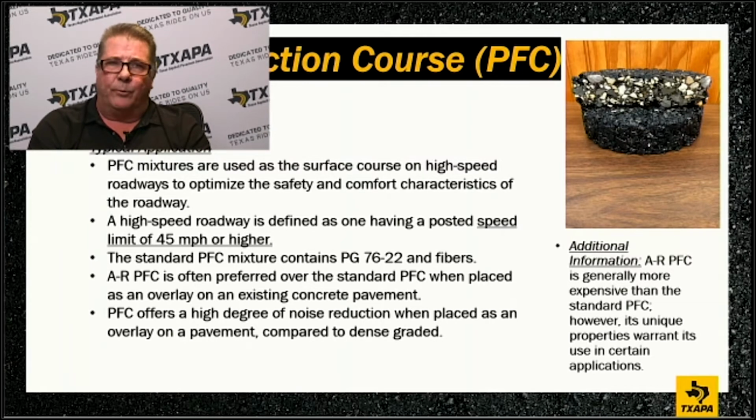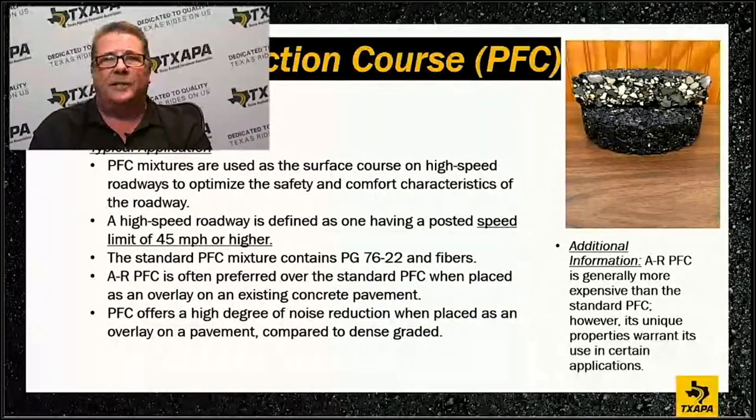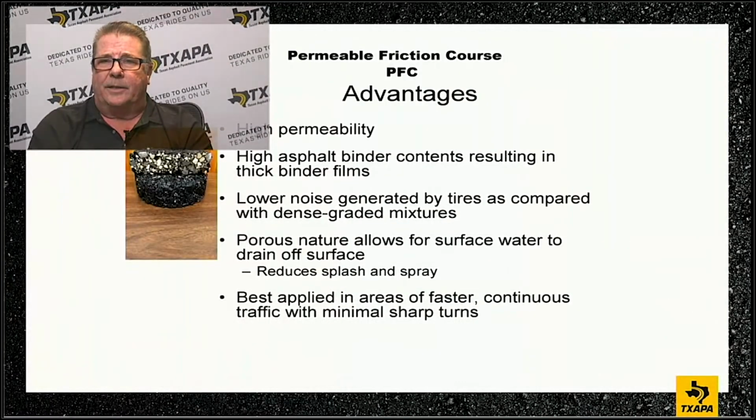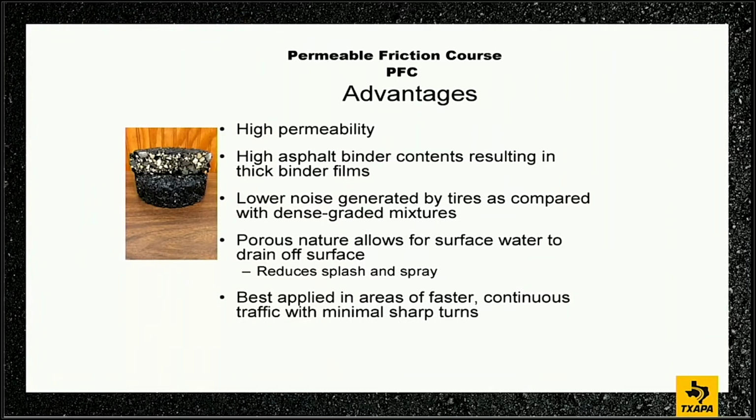And again, it reduces that noise. And when we're overlaid, it's way more quiet than dense graded mixes. Again, it's not a silver bullet, but it is a great surface mix to utilize when you engineer it correctly. So you pavement design engineers out there, look at that. It has to be engineered correctly. A great tool in the toolbox.